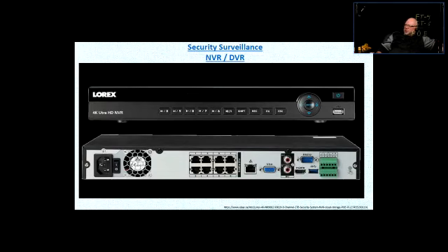It says 48. Up to how many volts? The PoE. PoE can be 48 volts usually, but there are other PoE systems that are 24 volts. Okay, usually there's 48 volts, but just to make sure, whatever system you got and whatever system you're purchasing, make sure that what is needed is actually the thing that you're buying. Right? Look at the specifications. Can it run through Ethernet? Yes, it does. Right? That's the idea of PoE. And usually the standard is 48 volts.